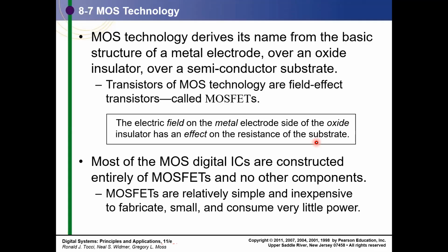It used to consume low power, but had also low current driving capability. Typically the IOs, which are the input and output nodes of the device, especially the output node, which has to drive an output capacitive RC load, were not very fast. So they were least preferred. But in today's technology, this has been overcome, and now CMOS offers much more current drive as compared to BJT. Any challenge can be met.